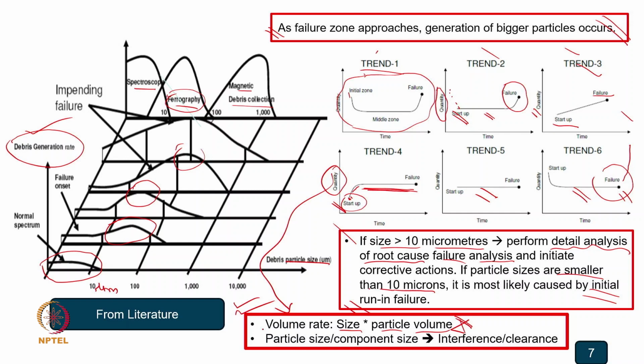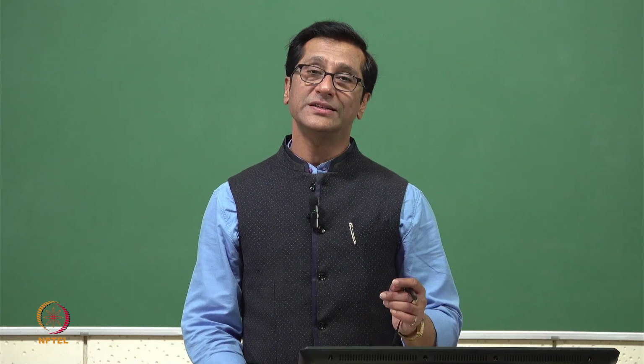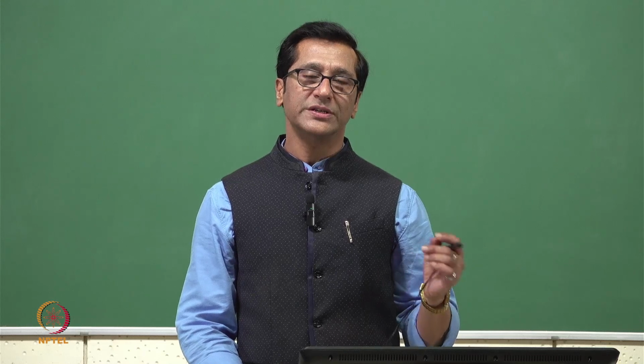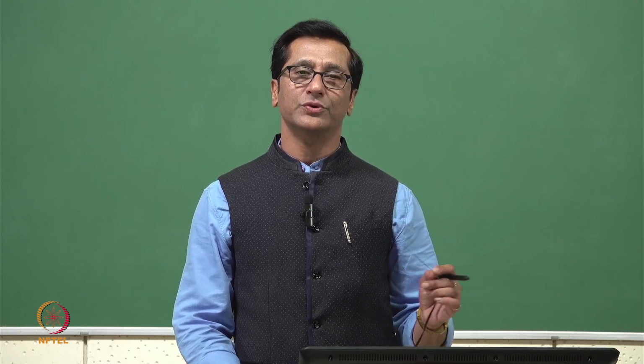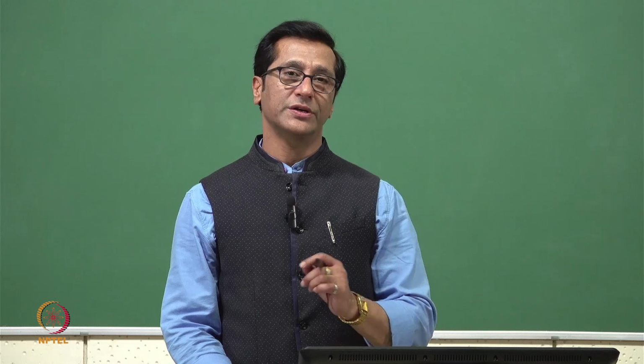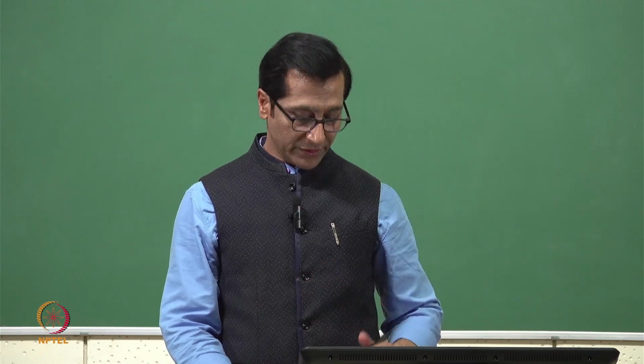One more thing comes when we are talking about the 10 micron. Instead of that, why not we give it as a percentage? If I kept 50 micron as a clearance or interference, what is the percentage which is justifiable? Okay, up to 0.1%, we don't have to worry. After that, it is really going from ultra mild wear to severe wear or mild wear. We need to think from that.